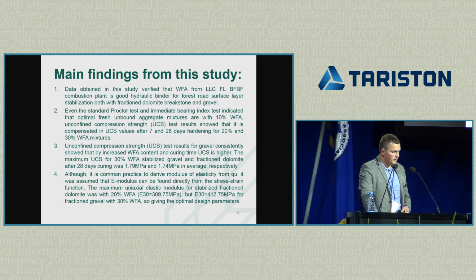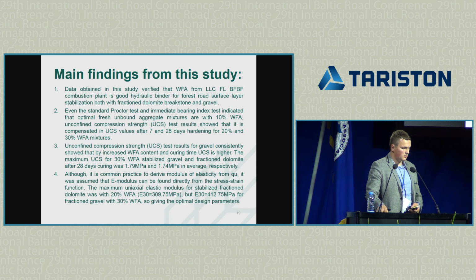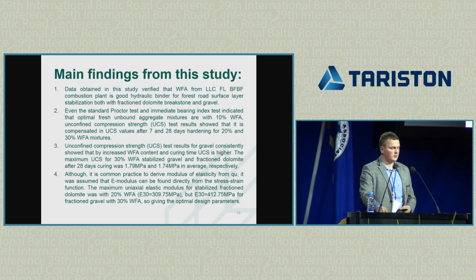And the final conclusion of the findings was that the common practice for design purposes is to obtain the modulus from the UCS value. We tried to get it by LVDTs for direct measurements, and here you can see the values we obtained.